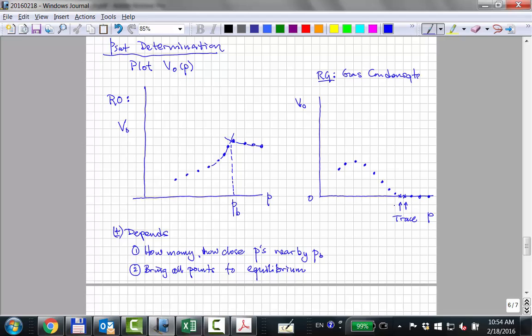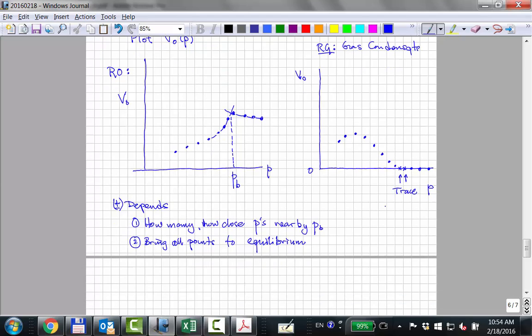And then they have to do some kind of interpretation of where the dew point is. Okay, so these 3 points here had 0 amount of liquid. So the dew point should be less than that. But the first time they got measurable liquid was here. Okay? But somewhere in here is the first epsilon little drop of liquid, right? So somewhere in here is what they will report as the dew point.